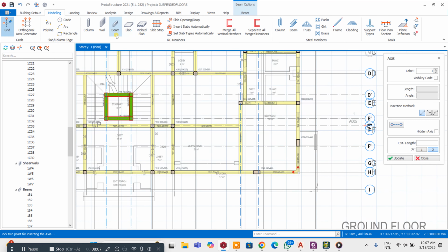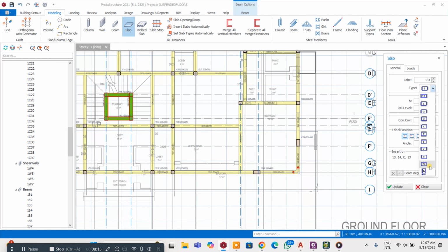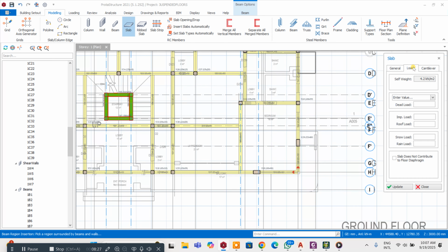Like our first design here, I'll be teaching how to use your cantilever slab. So we just change to 9, and we'll change to 12. This is a cantilever slab. See the cantilever here. The thickness of a cantilever, we want to use 175. Then the load is going to be a balcony. Then I will enter cantilever length as 1,200, and then my load is 9.3.